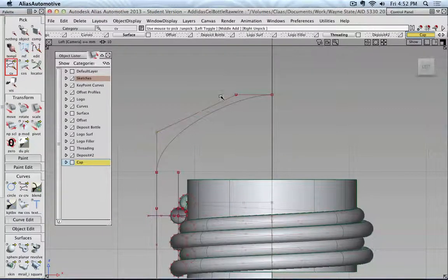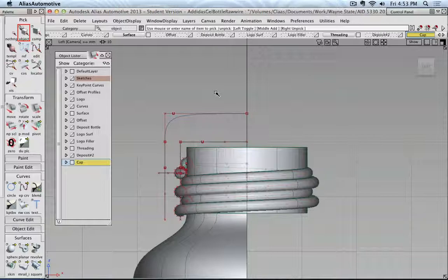And with this done, then I could select those 2 points and move it maybe down along the z-axis, and maybe at this point I move in, and you see I'm going to tighten this fillet a little bit. So it's basically like a hand sketched fillet for me. And one curve is missing. Left click and with the control button, and left click with the alt key pressed. And then there basically is the major part of our profile.